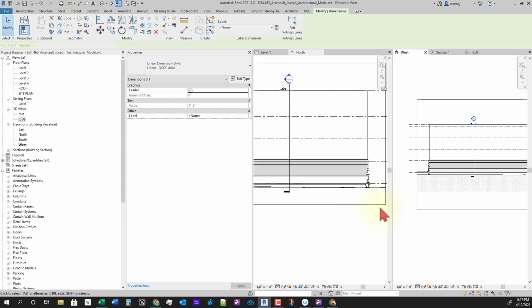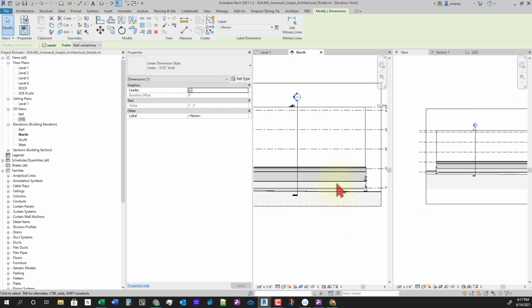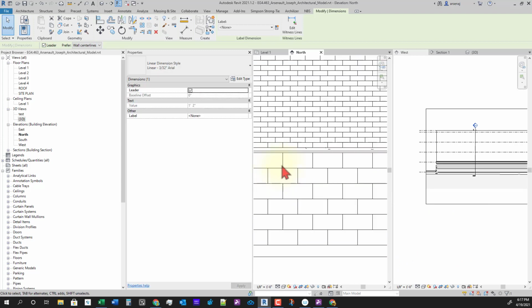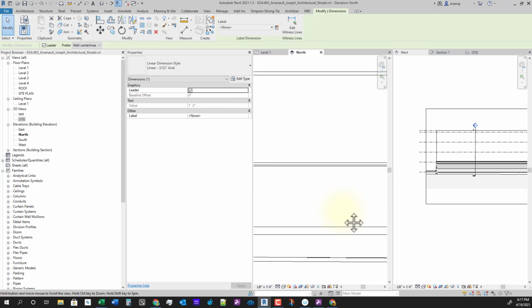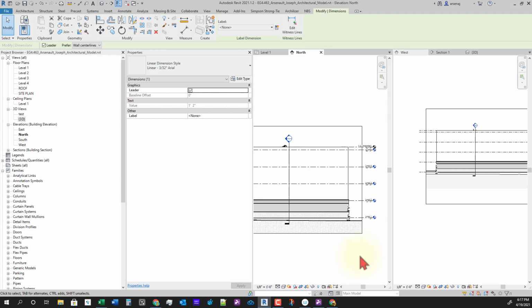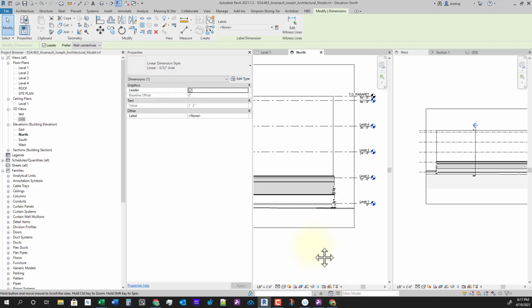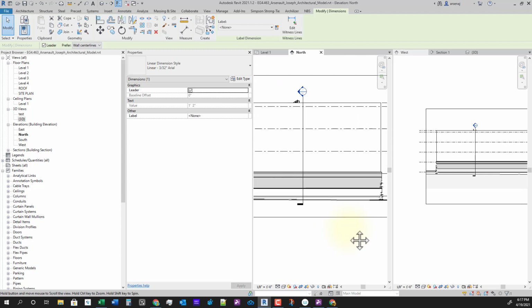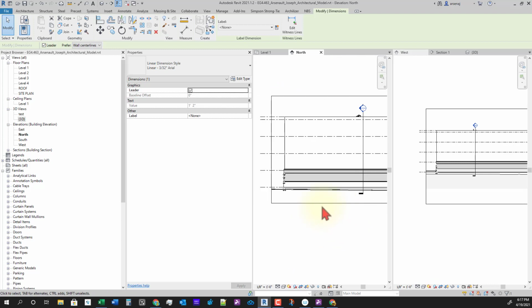So now when we start putting in windows, we have to think about that we would want to put in windows within a spacing that hopefully works with these bricks. You can see how they line up here at these points. So you would want to put your window opening such that it would line up with the coursing. So that, again, it's less work for the mason. It's also less materials, because if you're wasting a bunch of weird brick cuts, then that just costs a lot of money and wasted material.